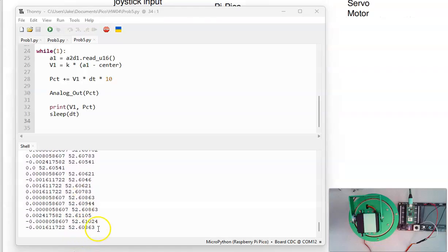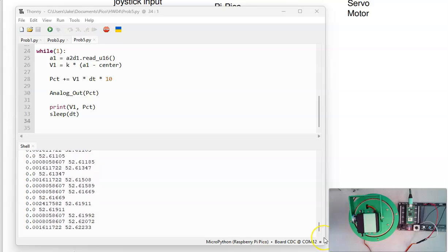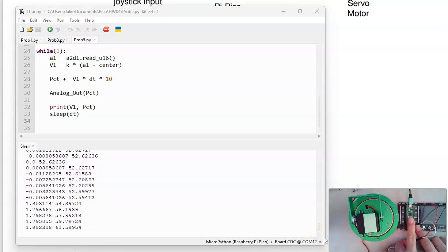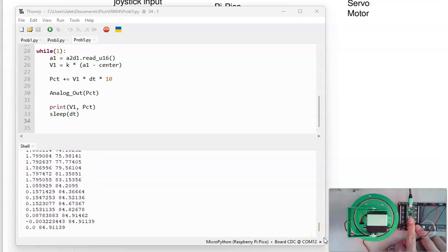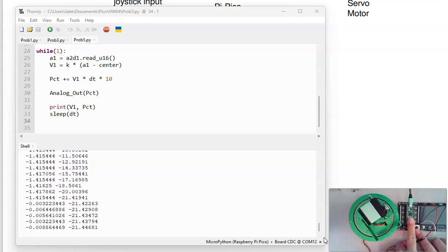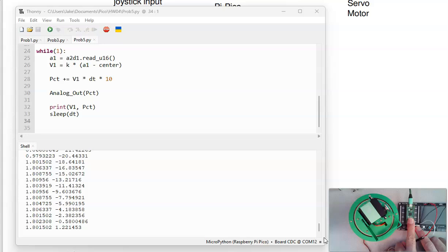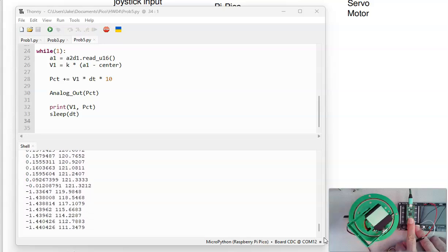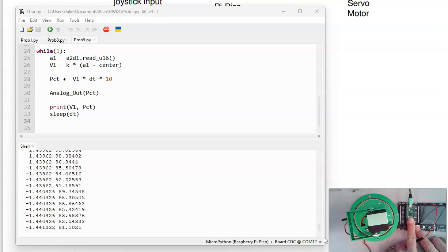So this one is a little bit different. If I move the potentiometer, I'm going to see the percentage going 0 to 100%. What I'm doing is I'm changing the pulse width. When I get down to 0.5 milliseconds, that's all the way in one direction. This is pulse width all the way the other direction. To 100%, that's 2.5 millisecond pulse width. The pulse width controls the angle.